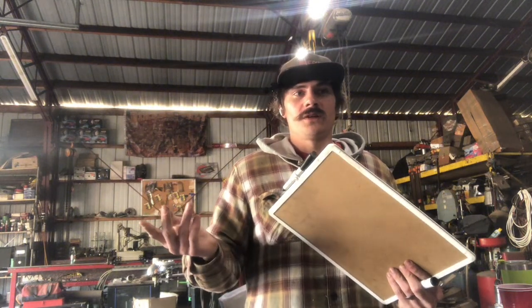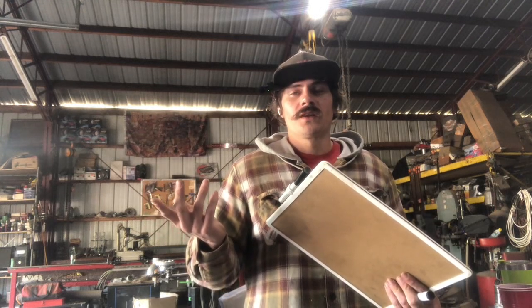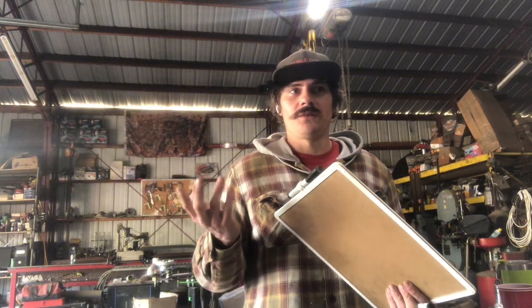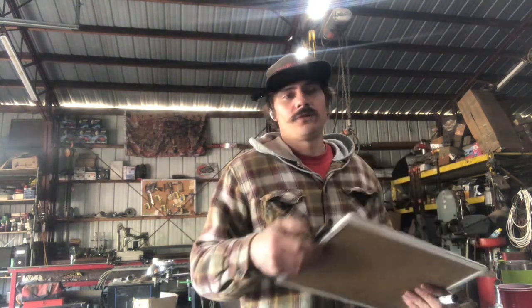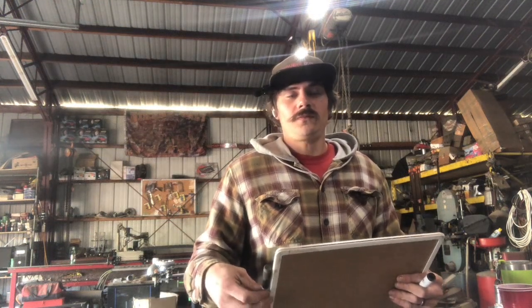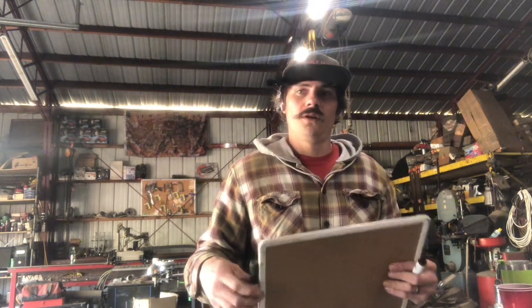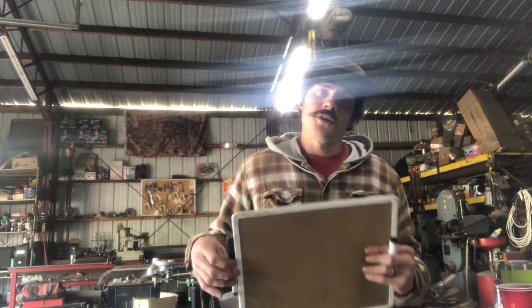There's not a lot of them published, and that's where the magic comes from with sizing turbochargers to applications. It's more about sizing the turbine side and housing to be proper for motor displacement and rev range, versus trying to size the compressor to be right. Compressors are pretty easy to size right. They all run pretty good. Making sure the turbine's good is a whole different world. Remember, your atmosphere is your engine.